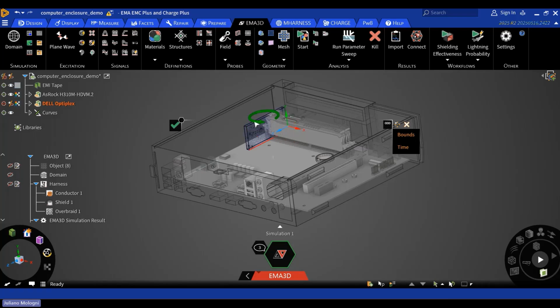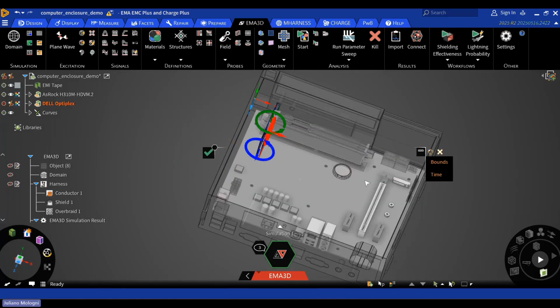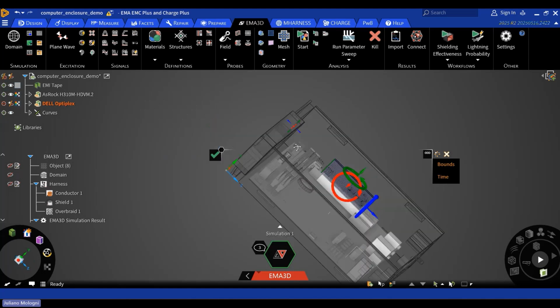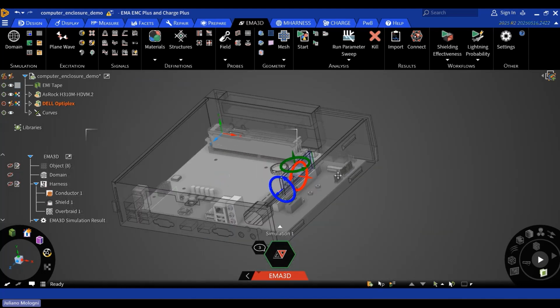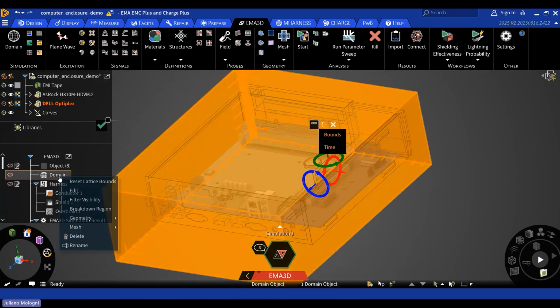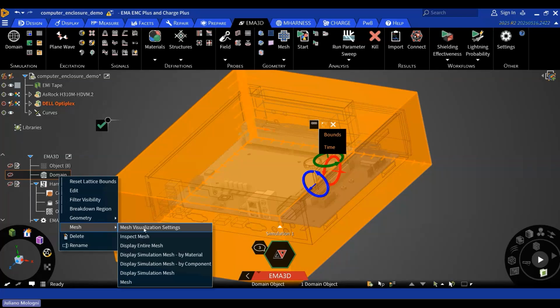Now you might be asking, can I simulate this PCB, everything in 3D, in EMC Plus or even HFSS? Yes, you can, but then it's going to take a lot of time. The whole idea here is that with a click of a button, you take advantage of the signal integrity workflow that you probably have in your company, right? And get those results and bring them into EMC Plus. Once you have them here, you place your PCB, you just generate the mesh. You can actually solve and get radiated fields.